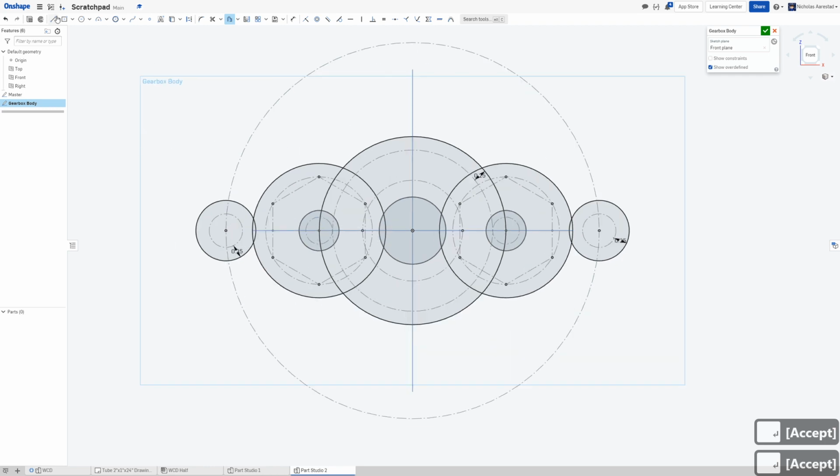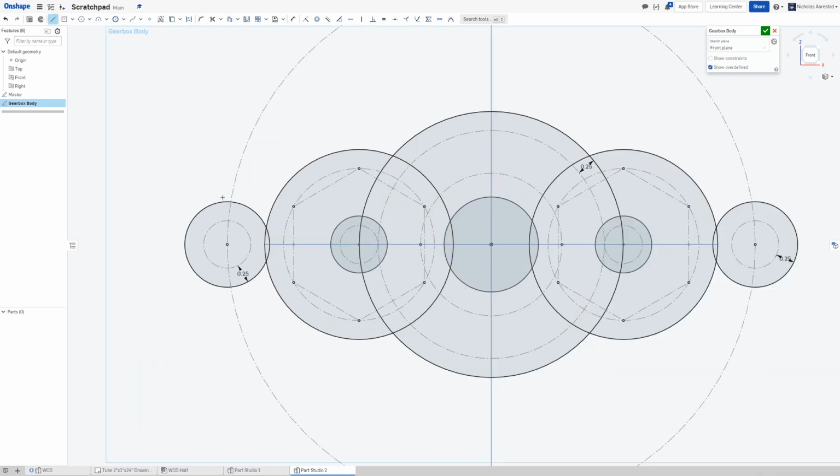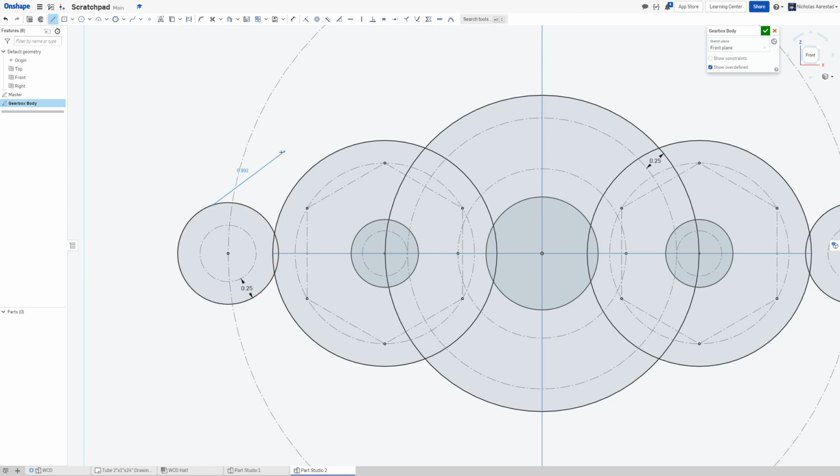And we're getting close to some geometry that we'd like. So now what I'm going to do is actually intentionally avoid some constraints here. So you'll notice I'm dragging this around. I'm being a little bit careful about how I do it to avoid being tangent to something that I don't want it to be tangent to.